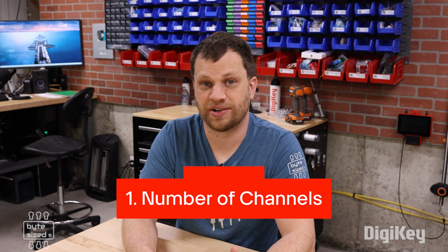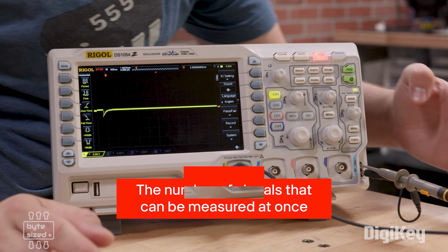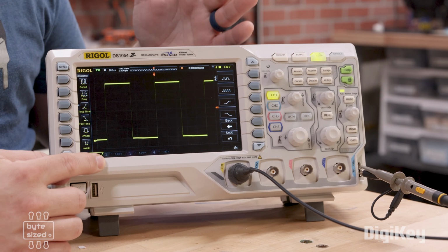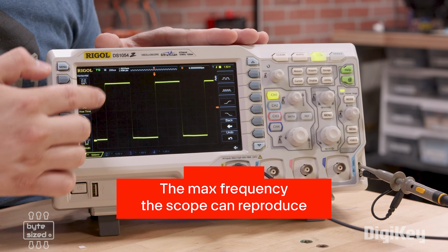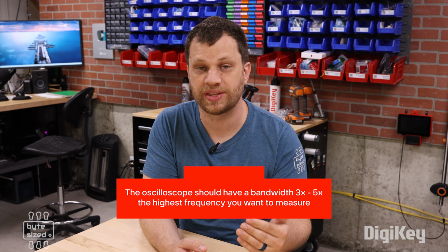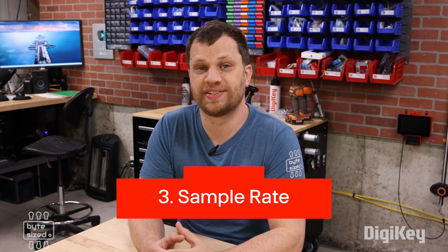First is the number of channels. That's just the number of signals that the oscilloscope can measure at once. The second feature that differentiates oscilloscopes is bandwidth. The bandwidth rating of an oscilloscope is simply the maximum frequency that it can reproduce faithfully. As a rule of thumb, you want to get a scope that has about 3 to 5 times the bandwidth as the highest frequency you're going to measure. So for example, if you want to measure a 25 megahertz signal, you'll need a scope with a 100 megahertz bandwidth.